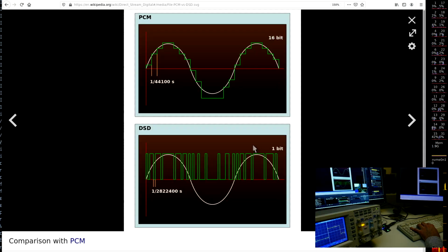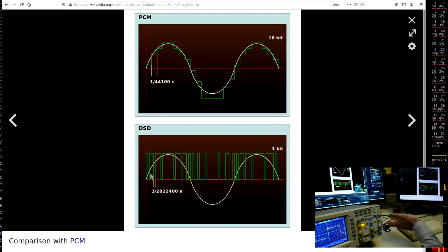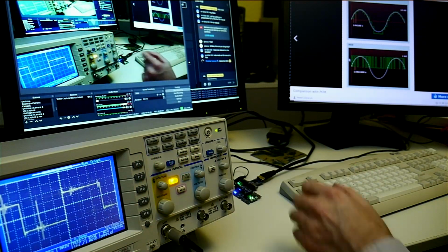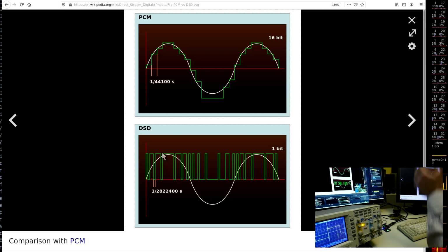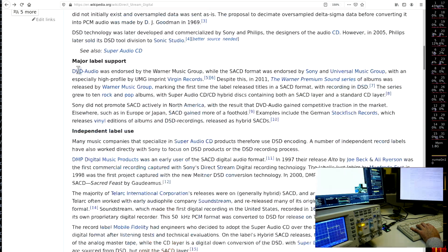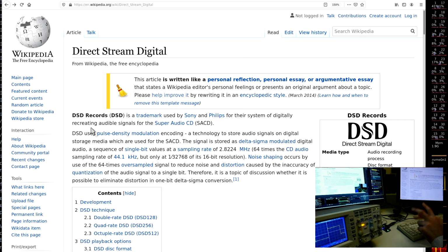So for us this means, of course, this is super simple to do, right? We have here an FPGA, we have some clock, the base clock of our system right now is 12 megahertz. Of course you could use whatever else, but given we have some clock frequency and something to output, we can certainly turn the bits on and off and build ourselves, poor humans, 1-bit digital, direct, what the heck was it, direct stream digital, live on a couple of euro or dollar FPGA.